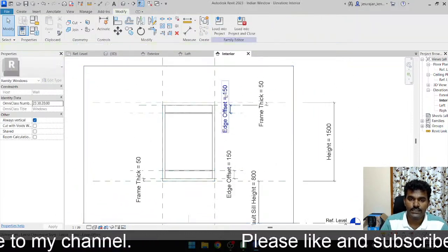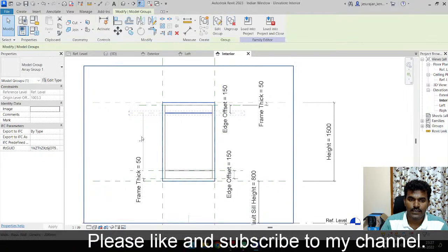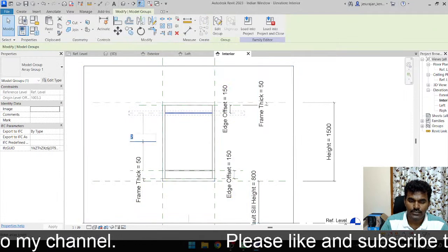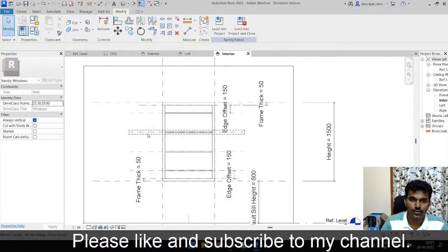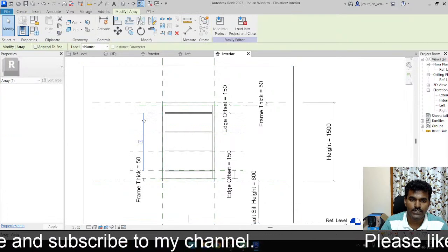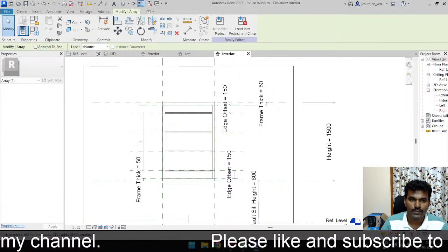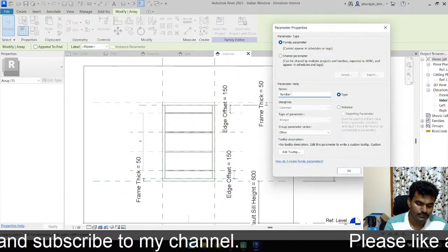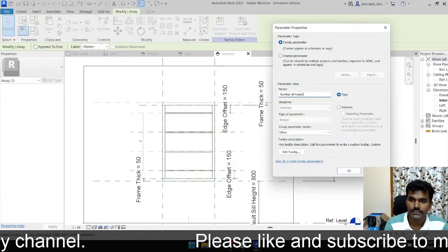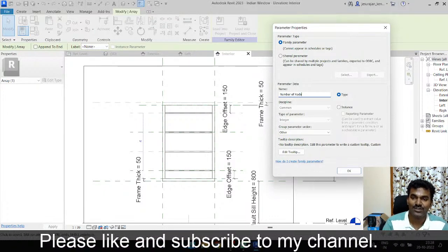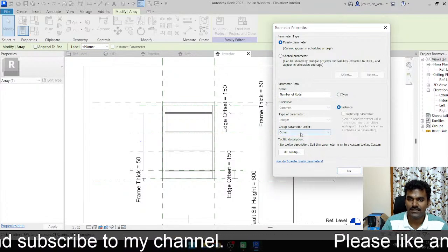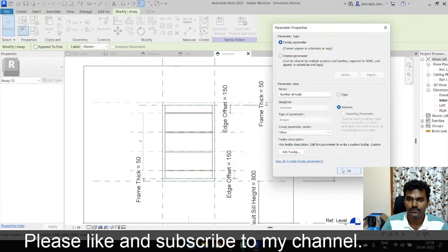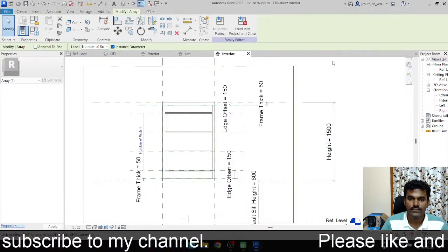Okay, you can see here 150 offset we got, and the number of array, you can change to 4 or whatever number you need. So to change the number, I'm going to add a parameter and name it as number of rod. Rods. Okay, instance, other, let it be other. You are here, Kishore, thank you very much. Okay, the number of rod.